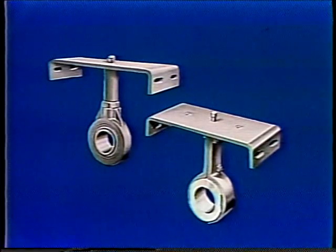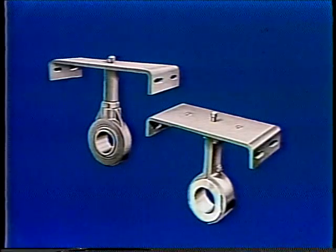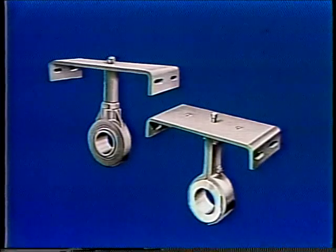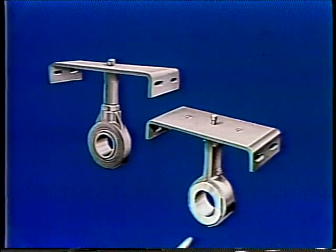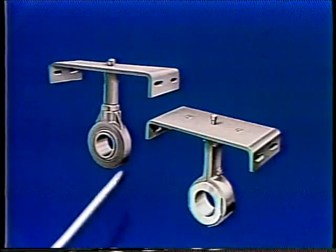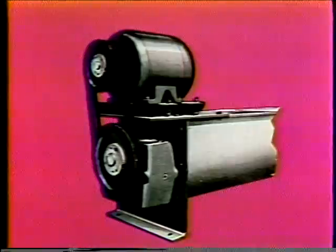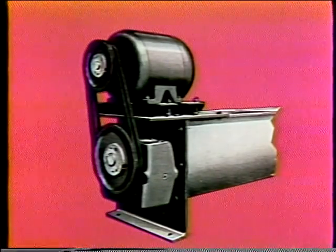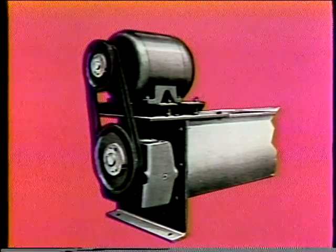If the conveyor is more than one section long, the unit must have hangers. These are T-shaped brackets that have bearings on them. The bearings usually will be either sleeve or ball. The drive is frequently a shaft-mounted reducer, as you see here, but can be either a parallel or worm reducer, which may be direct coupled or chain connected to the conveyor.